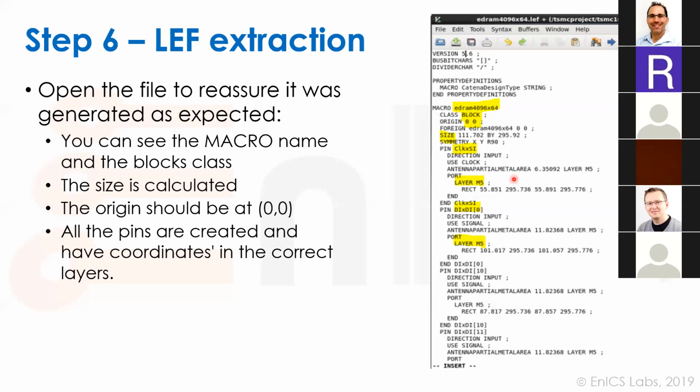Yes. So if I have a little bit of metal and a big gate, it won't burn it out. But if I have a lot of metal that's not grounded through any other way, and it's touching one little tiny minimum transistor gate, there's a good chance that during manufacturing, it'll burn out the gate. So I don't want to ever come near such a thing, and there are ways to get around it. For instance, if I just add a reverse bias diode, the diode will break down before the gate, and that's fine because it doesn't get ruined. It just brings the charge to ground.